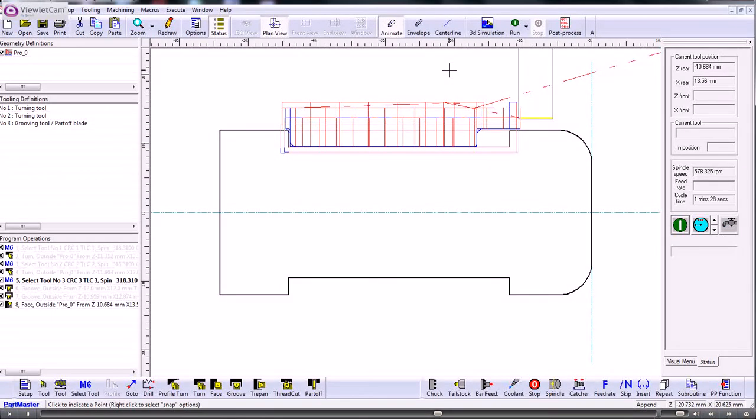Okay, so those are the types of operation that you can use, either using the roughing tool with left and right options to machine that. You can use a grooving cycle and add on the fillet and chamfers to the tip and root as you need to, or you can let it machine it based on the geometry that it finds. Now the geometry that it finds can be any geometry. It doesn't need to be in this case a rectangular groove. It could be something with a big radius at the bottom of it. So that's how that works.